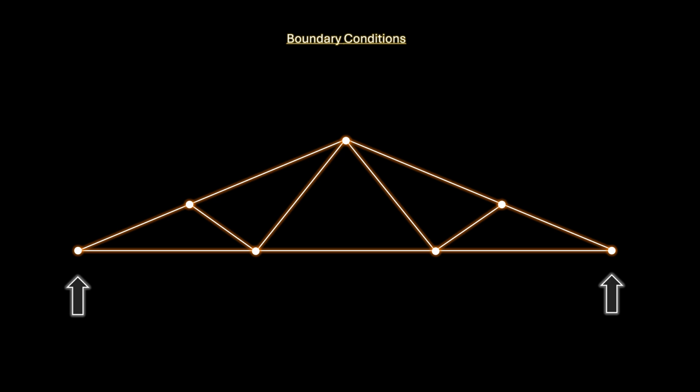Since we do not need to constrain the truss against rotation at the supports, we will not provide any fixity against moments. Therefore, the truss will not transfer any moments or moment couple to the wall. We will therefore use pinned connections. A pinned connection cannot transfer moments but will transfer vertical forces and lateral forces.